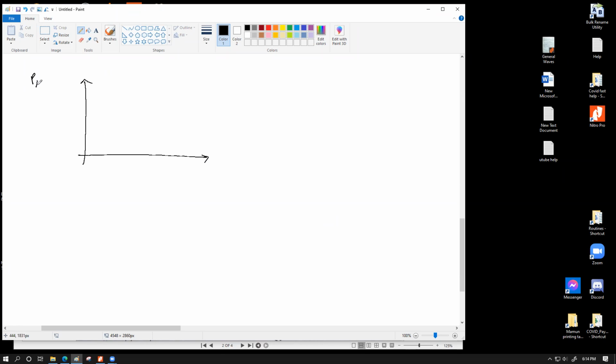If you plot a graph of load versus the load resistance, let's say you have a fixed source which has a fixed EMF of E. Let me show you in the actual format. The way we represent a battery with internal resistance is that we draw a dotted line around the battery, and inside the battery we represent it by a small resistor like this, within the small dotted rectangle. This is usually labeled as small r, and the EMF is usually written anywhere outside, on the top or bottom, it doesn't matter. So this is a battery of EMF E and internal resistance r.